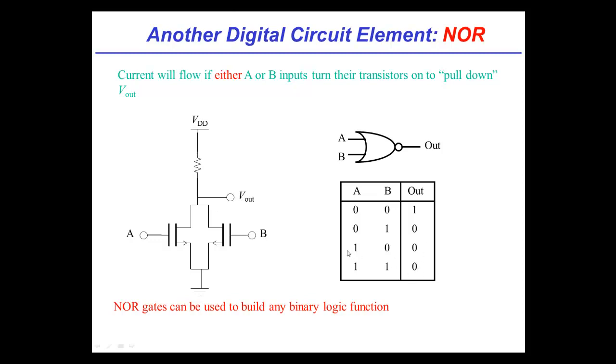So it looks like we've been able to do NOR gates, NAND gates, and inverters. We basically have everything we need to start doing Boolean logic. That's true. If you remember from some of your classes, and if you don't, you'll probably take them soon. In fact, with these gates, and in fact a subset of these gates, you can, in theory anyway, build any logical function, any combinational logic function you might be interested in. So it's pretty powerful that you even know how to do this with these simple transistors.